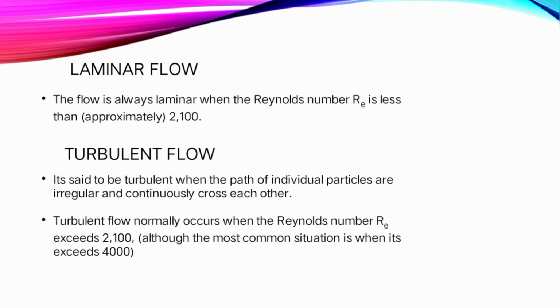On the other hand, it is practically impossible for turbulent flow in a straight pipe to persist at values of Reynolds number much below 2100 because any turbulence that is set up will be damped out by the viscous friction.